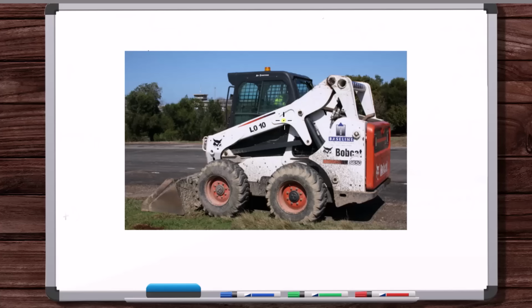So what would happen is it would be twisted in. You'd still have the pin force here. Maybe you do the same thing, but these pin forces all of a sudden wouldn't be at the same spot they're shown here. They would be over here because it would be twisted in, right? This would be caved in. So instead of being straight up and down, you'd have a pin force pointing out of the page and down, and another pin force pointing, I guess, into the page and to the right. You have to specify all those directions.